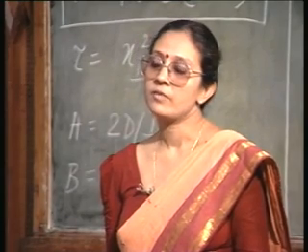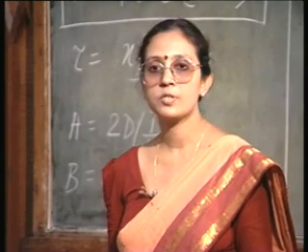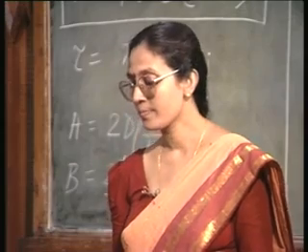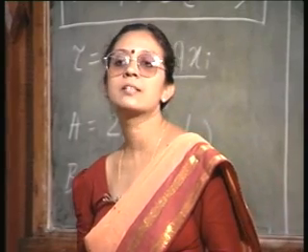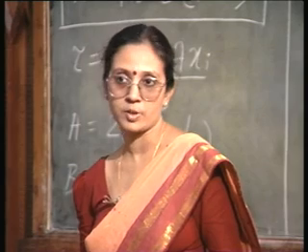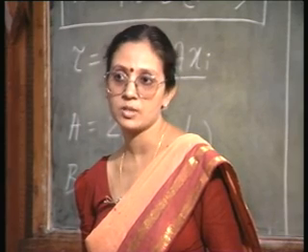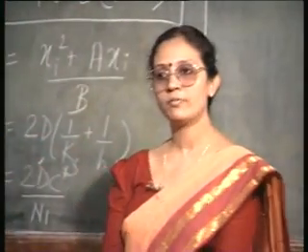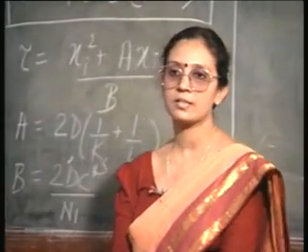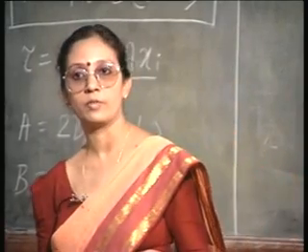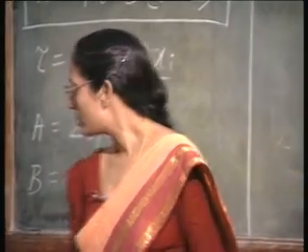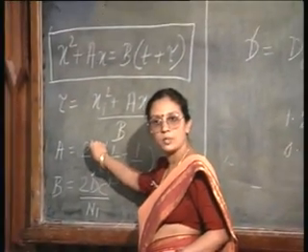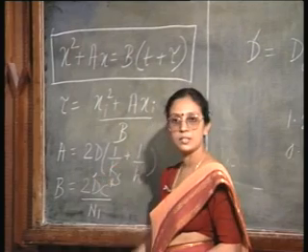But there is one very funny problem. What happens to A? If you notice, A actually decreases with temperature. In this particular example that I have taken, A actually decreases with temperature. At 920 degree centigrade, A was 0.5, and at 1200 degree centigrade, it has decreased to 0.05. Why should it be so? That is because A has D in the numerator and Ks in the denominator.